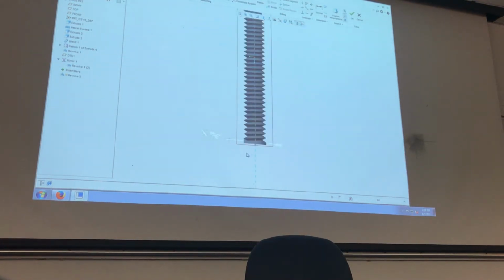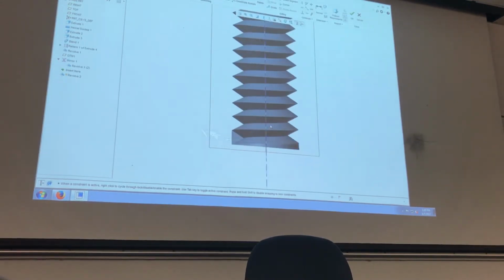Down here, I'm going to go ahead and add my center line in, so I have something to revolve around. I almost forgot. Then I'm going to draw a line. And I'm going to do the first line right about here. And I'm going to move across, click off of it, so I can set my scale. I'm going to use 0.1. Okay.